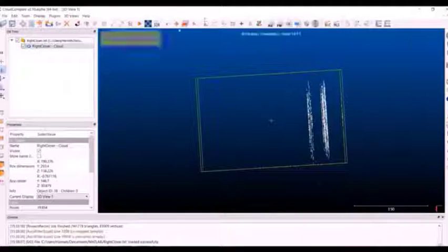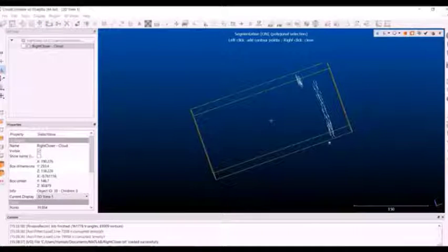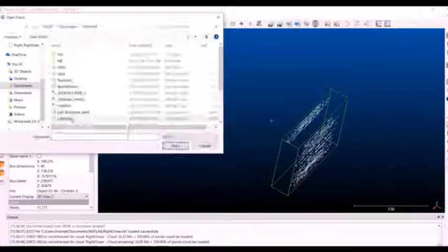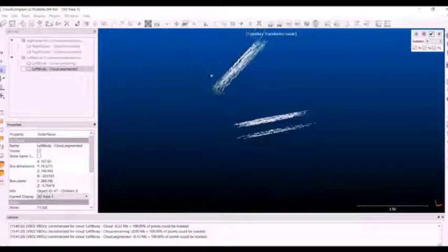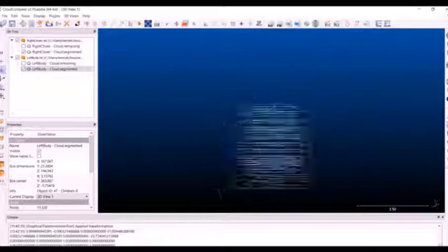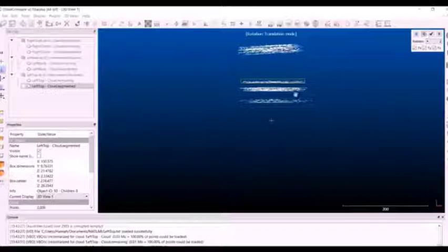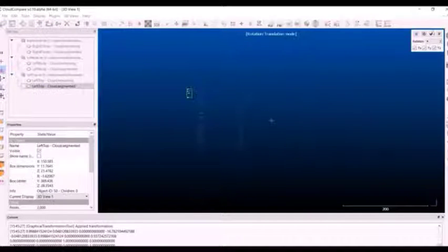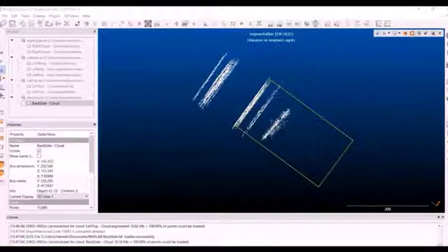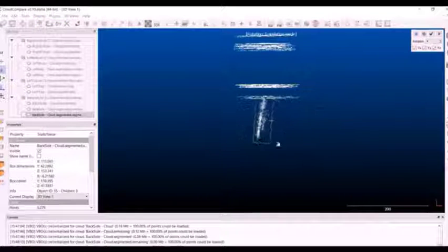Originally, I had done this filtering along with the rotation and stitching together of the 3 point clouds in Cloud Compare before generating my mesh. Cloud Compare has a lot of intuitive tools that allow you to do this filtering and stitching by hand, including a snip tool to remove points in areas where they don't belong, and a translation and rotation tool that allows you to orient multiple point clouds with one another. However, writing the MATLAB code to do this for you is a much cleaner and more automated method of achieving the same result. It also can take into account the location at which data was collected from in order to more accurately align individual point clouds.